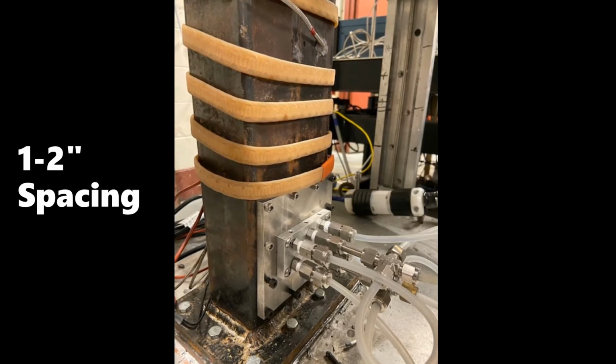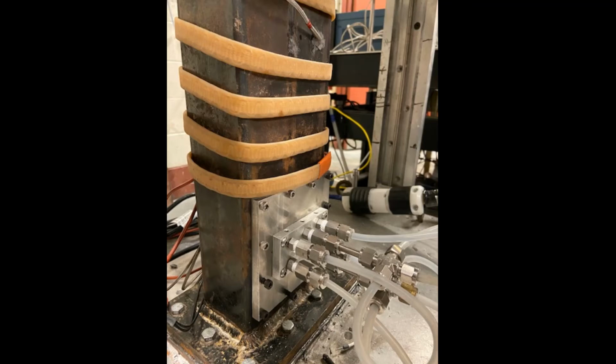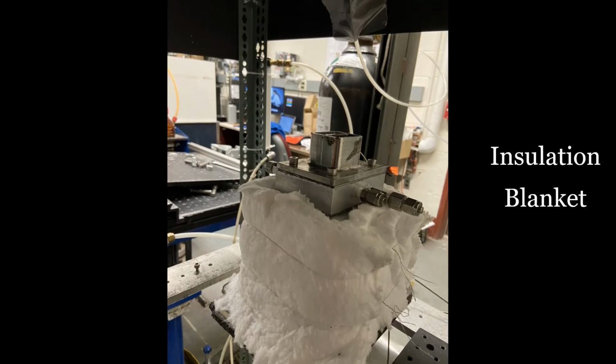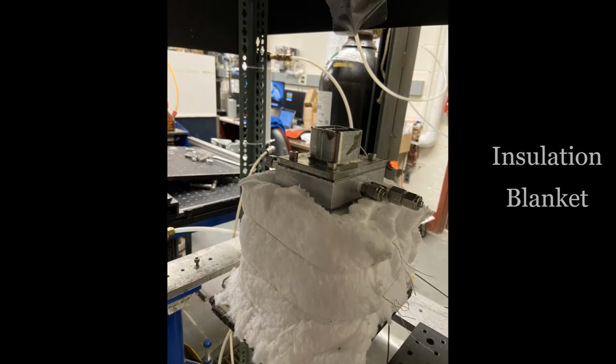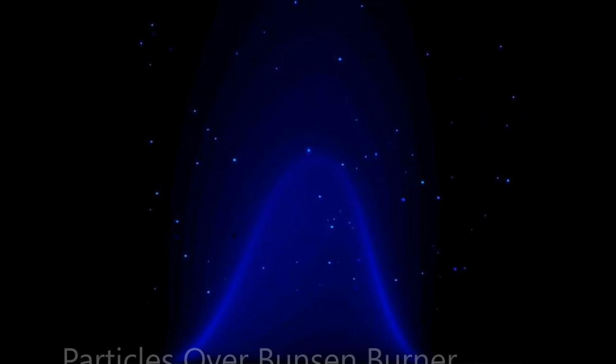These heating tapes are wrapped around the walls with about an inch or 2 of spacing between the next layer. The heating tapes and walls are insulated with an insulation blanket that is held together with wire. The next step to complete this year's objective is to check the bluff body for fuel droplets that do not vaporize in the rig. This can be monitored by creating a laser sheet of 532 nanometers over the bluff body and taking images with a solo PIV camera.